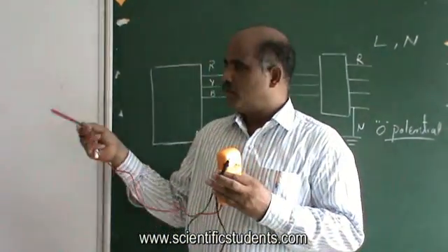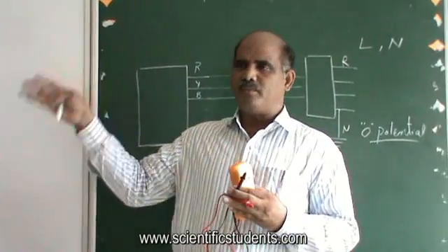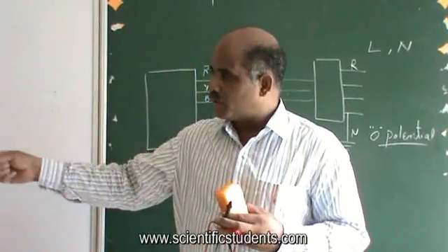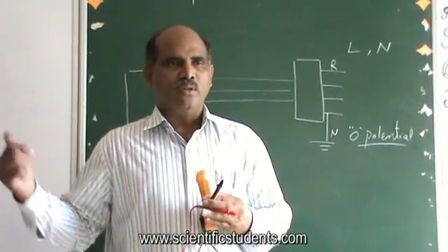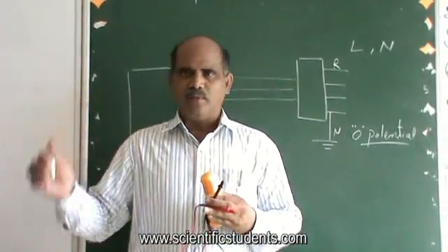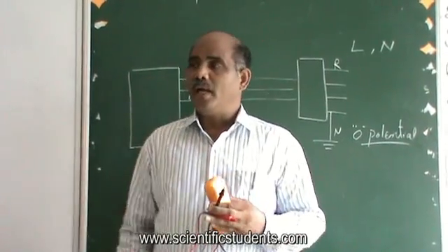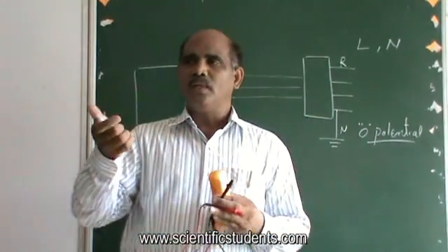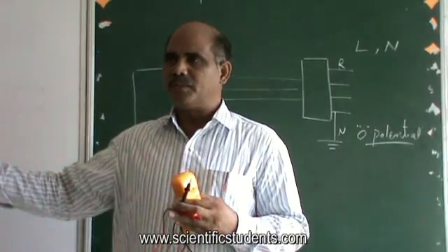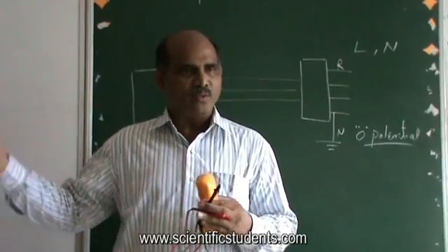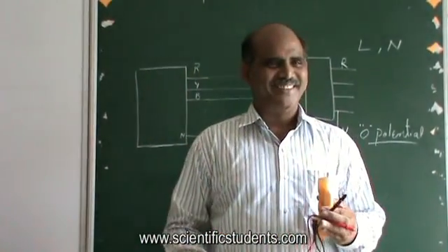And here, though the three-phase system has come into our school, from the three phases they brought only one phase here. Neutral is common all across the building wiring. And then they just brought one phase here. So whatever the voltage difference between that phase brought into this classroom and the neutral is the voltage we have here in the class.